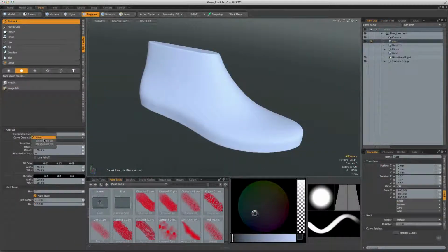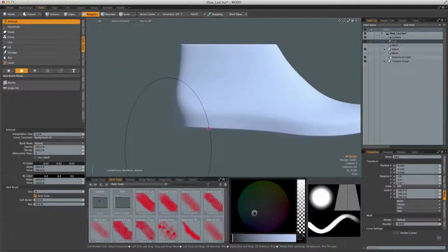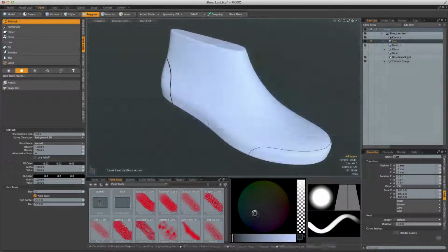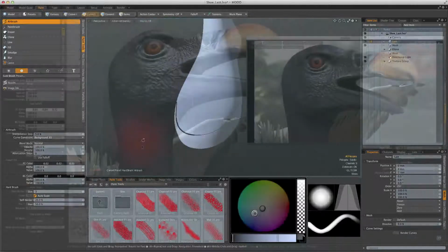If you want to apply a very controlled mark to a surface, for example to draw a thin line over a complex 3D form, you're able to constrain a brush to either a 2D or 3D background curve. And if you have auto scale active, the brush tip will scale relative to the scale of the object in the viewport, allowing the mark to maintain a constant width.